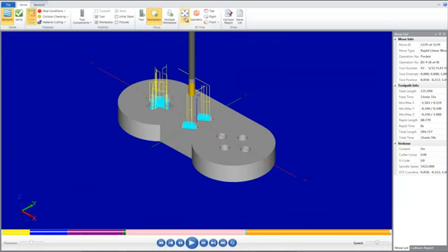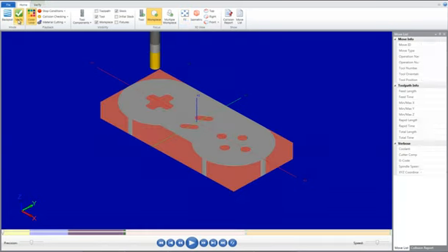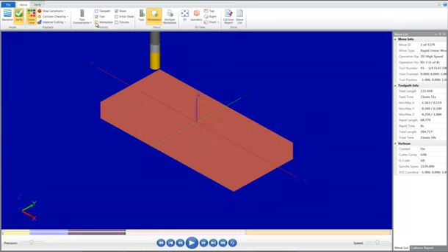We will now simulate the toolpath in Verify. From the Mastercam backplot home, select the Verify button. Disable Workpiece. Ensure that the following are enabled: Tool, Stock, and Workpiece. Verify mode shows the path the tools take to cut the part with material removal. This display lets you spot errors in the program before you machine the part.